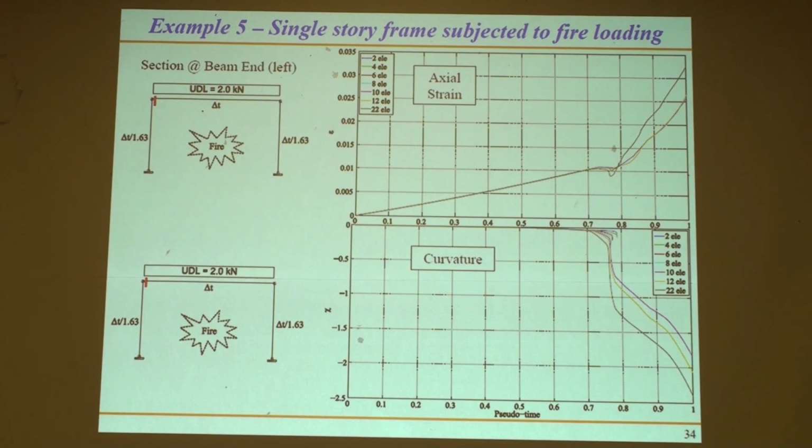localization problems. So, just like in reinforced concrete, or any problem where you're using softening, if you look at what the plastic hinge length is in your structure, this is a steel structure, but based on many tests, you can go and check what plastic hinge length you're expecting to have in your structure. You can impose that, and that will give you your element length and the discretization that you should use to get good results.